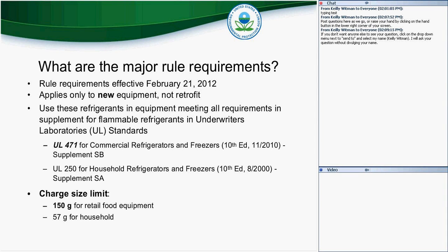And then I guess the other thing was that part of our way of looking at the risks is we say, well, what happens if there's a worst case situation and all of the refrigerant escapes from this piece of equipment rapidly, will we get a situation where it could be explosive or where it could burn? So we did an analysis. We said, well, what if we've got this room size? What if we've got this charge size? And it did pass at 150 grams.